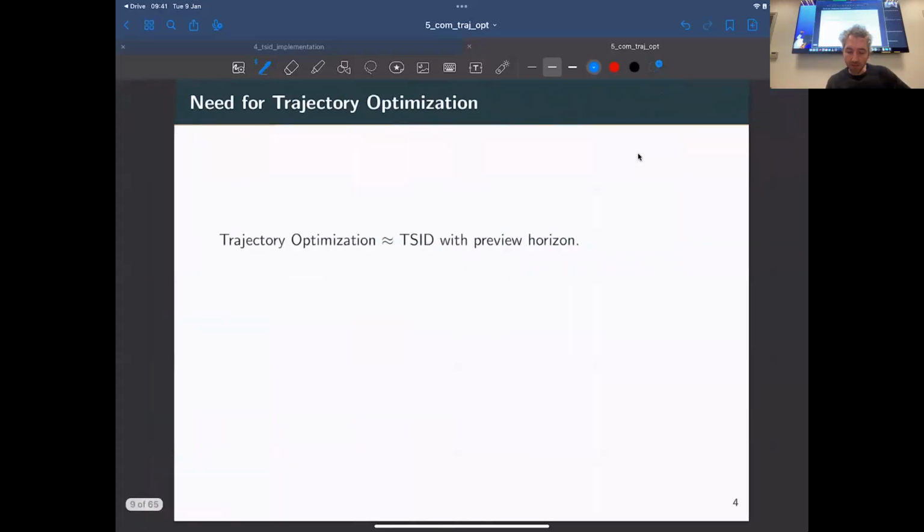So if you want to use a tool that solves this problem, that tool is trajectory optimization. Because with trajectory optimization, we are not only looking at what happens in these very moments, but we are looking at the future evolution of the system, because we are optimizing a trajectory. And so we can make sure that the whole trajectory does not collide with the wall, does not violate constraints. And so everything is going to be fine, not only in 2 milliseconds, but maybe in 10 seconds or something like that. We have a horizon, a prediction horizon.